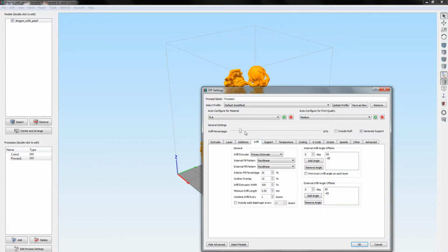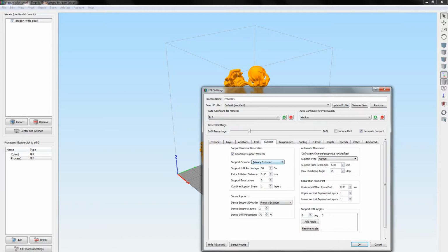Now, infill is what the slicing software puts inside of your print to give it more rigidity, or if you have surfaces that go beyond a 60-degree angle inwards on your print. You can choose the density of your infill based on a percentage value, where 0 is completely hollow and 100% is completely solid. Usually around 20% or so is ideal for most prints, and there are several patterns you can choose from, and they each have distinct advantages and disadvantages, but the majority of people either print using the rectilinear or the fast honeycomb.